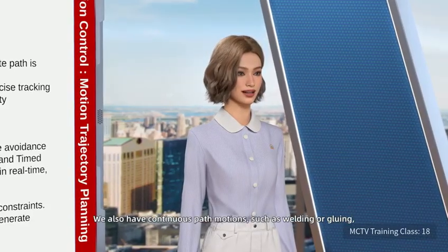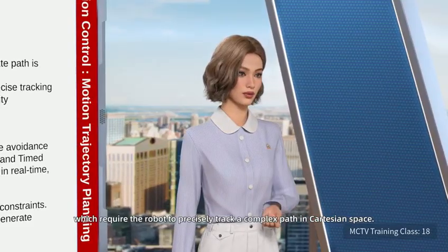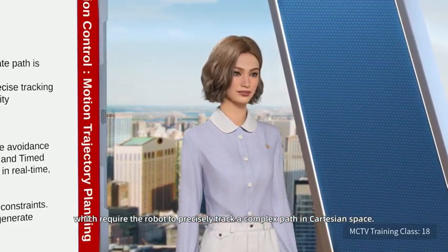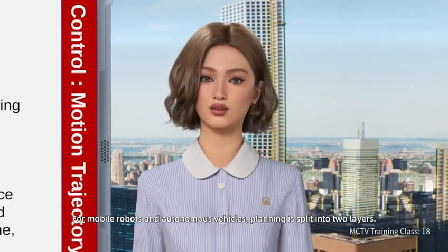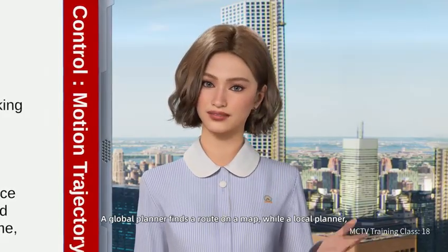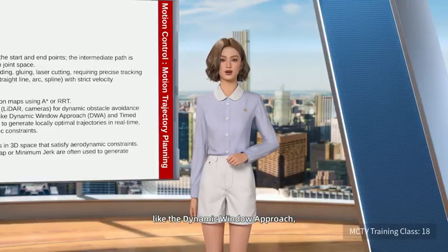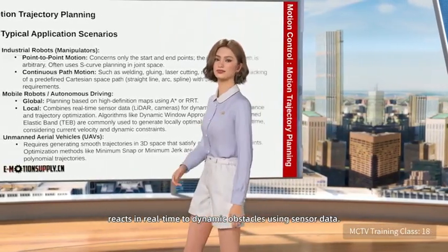We also have continuous path motions, such as welding or gluing, which require the robot to precisely track a complex path in Cartesian space. For mobile robots and autonomous vehicles, planning is split into two layers. A global planner finds a route on a map, while a local planner, like the dynamic window approach, reacts in real time to dynamic obstacles using sensor data.